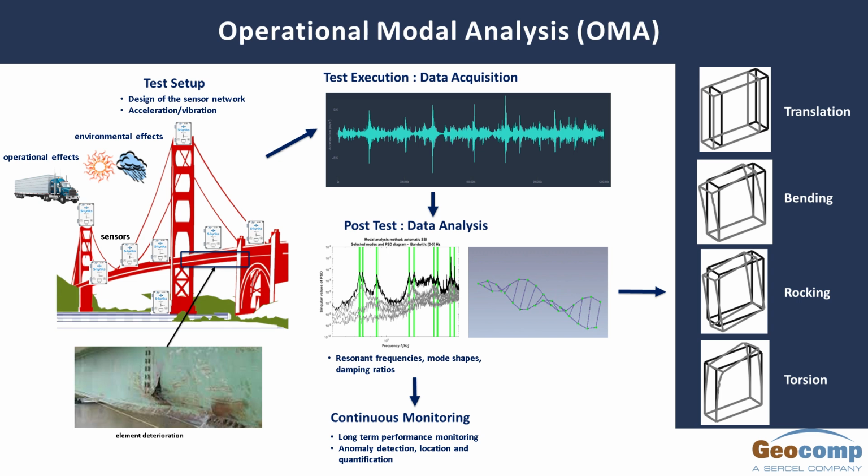This is the same analogy as when you owned, in the early 1990s, a nice tape recorder with a synthesizer with LED lights on it, and when you're playing music, it shows all those ups and downs. This is the same idea, but in this case the bridge is moving, and you are looking at those motions. Individually, what we are doing is decomposing that complex behavior into understandable modes, which we'll talk about, and those are generally in the form of translation, bending, rocking, or torsion. In the case of wind monitoring or wind performance, torsion is the most important case.